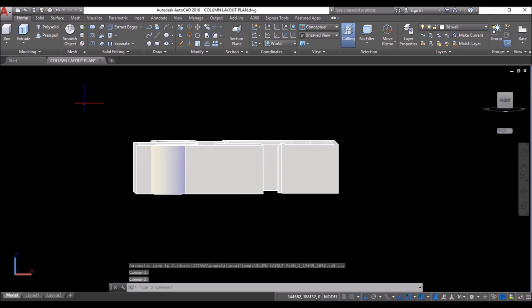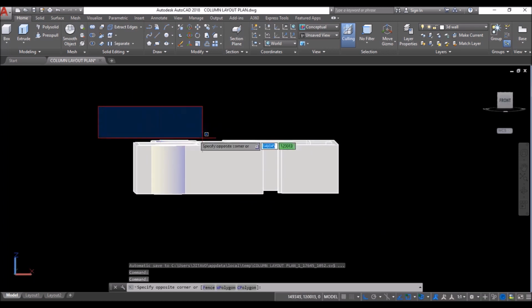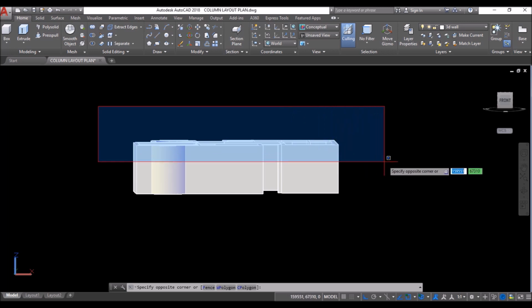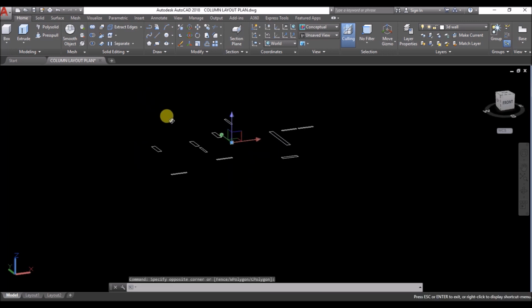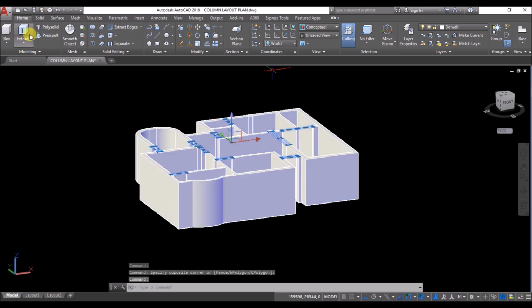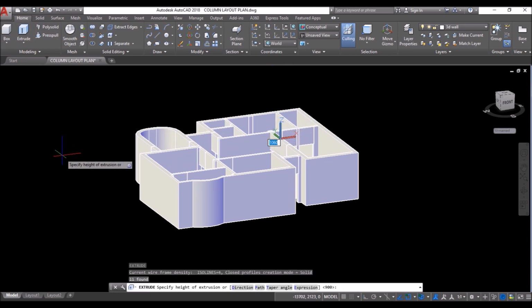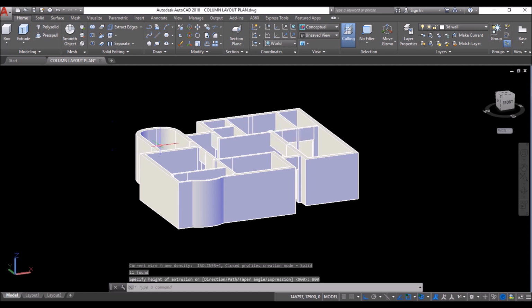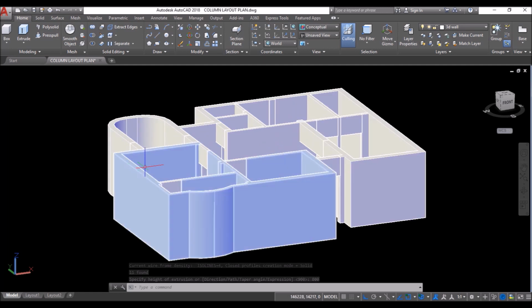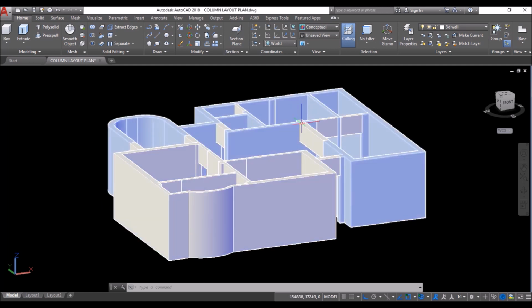is seen. Then select the rectangles by using blue window selection as shown. Then orbit the drawing again. Click on the extrude tool or type EXT and press enter. Move the cursor downwards. Type 800 and press enter so that the lintel level is at 2100 mm from the plinth level. Now I'll union the walls with these boxes.